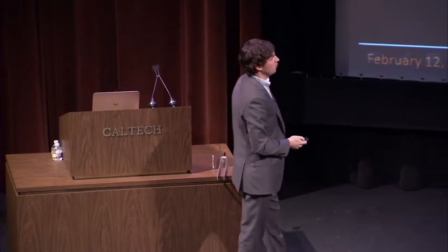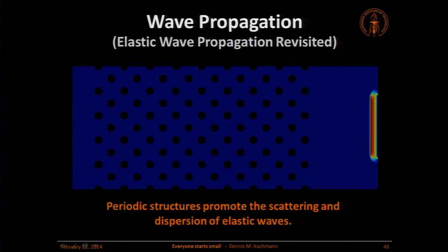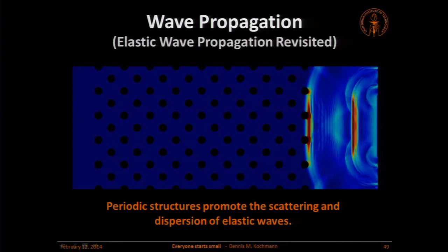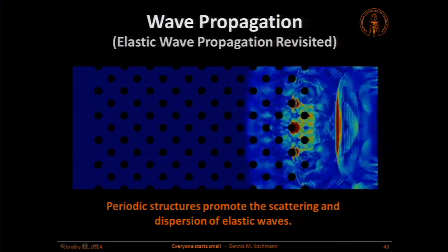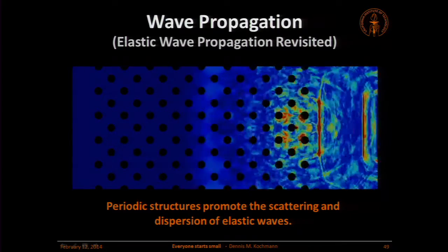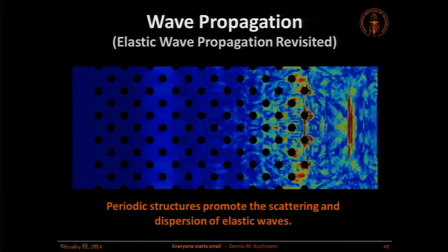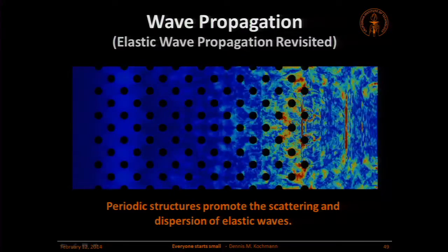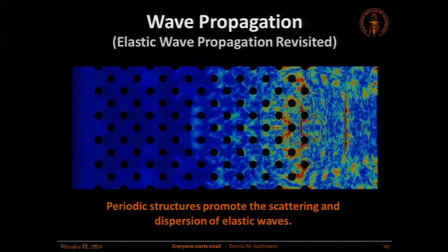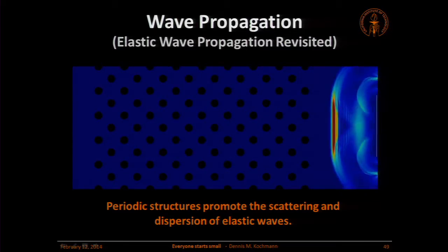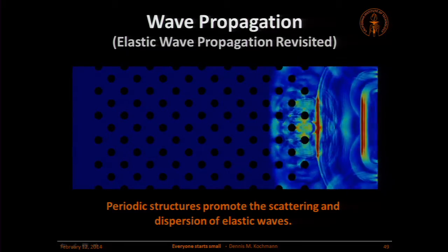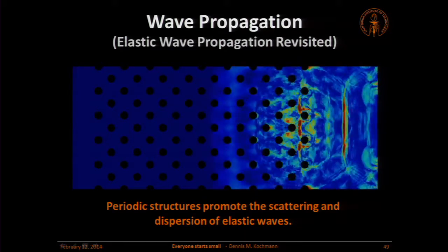These truss structures have very many interesting properties. One of them I'd just like to briefly mention here is damping. Remember how a while ago I showed you a movie which looked exactly like this, but it doesn't have these black holes. And we saw how the impact energy went through all the way. Now what we did here is a thought experiment. We made little holes into the material. This is still a copper single crystal, but we introduced periodic holes.